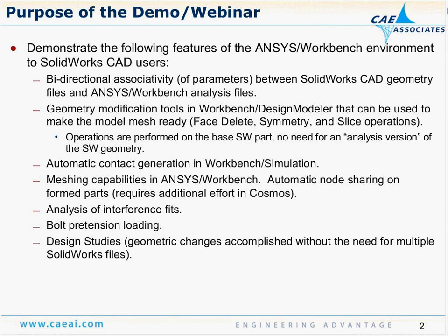And your mesh requirements will be governed by, in many ways, the resolution on the results that you're after, the type of loading that you may be applying, and other things like the type of geometry that you need to model. One of the things that we'll be doing today is making an assumption of symmetry, where we will cut the part, and our loads, our materials, and our geometry will all be reflectively symmetric about that cut boundary, which means we only need to analyze a smaller portion of the geometry. Design Modeler is very, very good for setting up those types of analysis features.